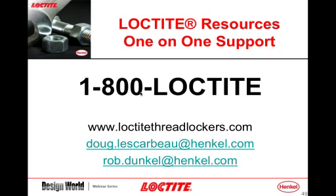With our products, typically anything loose should be removed. If you have the bolt, it's easier. You can just brush it with a wire brush. When you have the nut, obviously there's no easy way of getting inside. We normally just say use it as is. Make sure you clean off the bolt itself. Our product will stick to itself, and so when it goes in there and cures, it will still work effectively. You just don't want any large loose pieces or dirt in the hole itself.